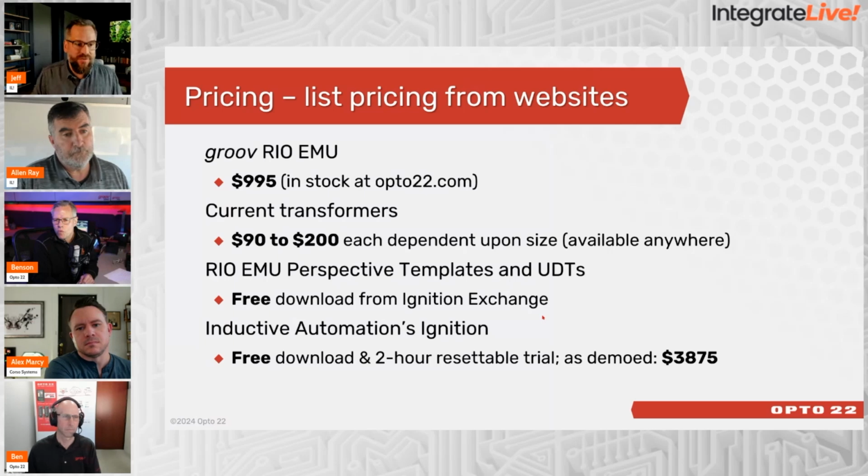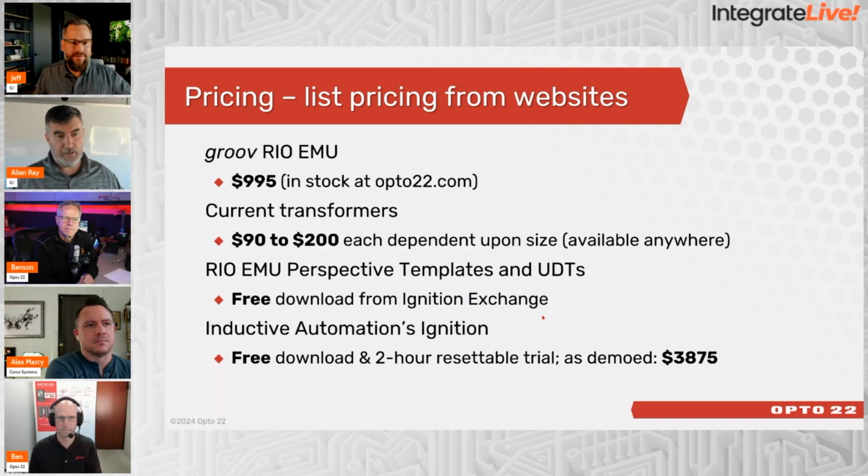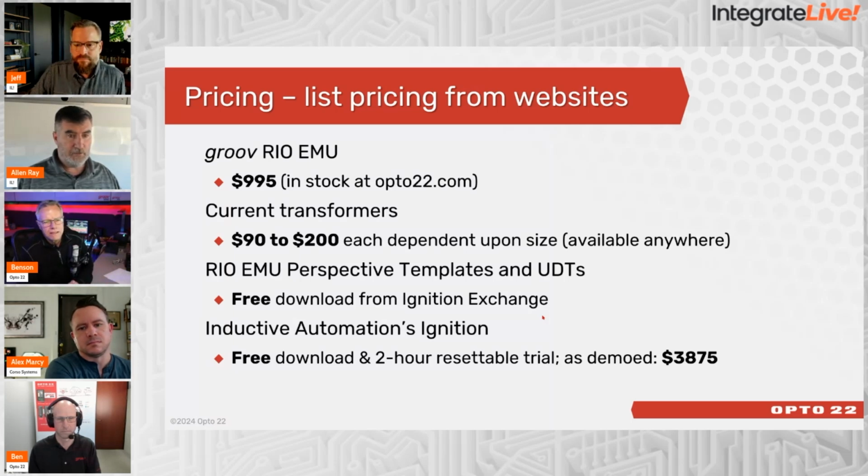Really, it's just the very first step. And you said it earlier, you can't manage what you don't measure. Correct. Well, think about power factor. Think about the heat that's generated and the damage you're doing to your equipment by not knowing what your power factor is doing. And so the reality of just having that information and knowing, hey, I'm dipping down in the low 80s, even getting into 70, you're taking life out of that equipment. And so again, knowledge is power.